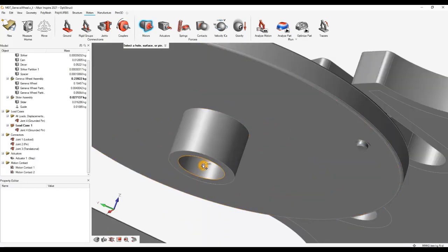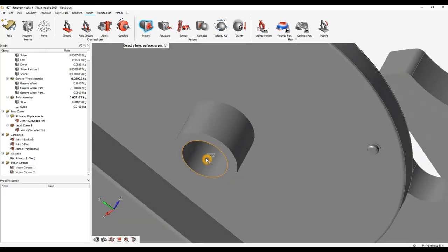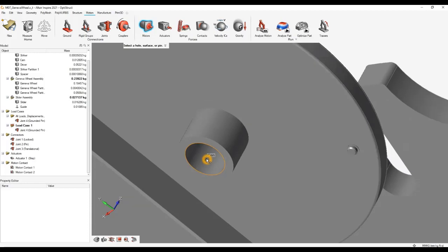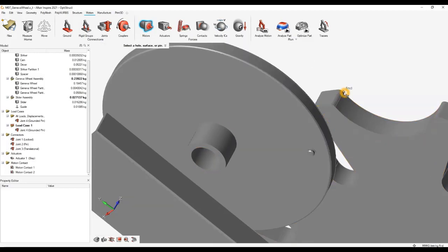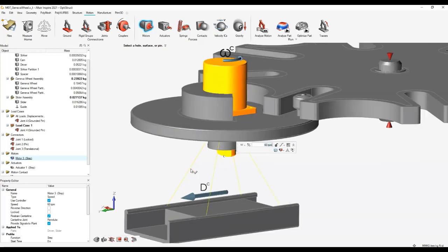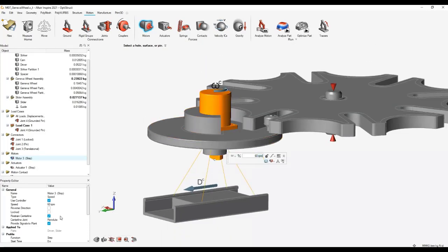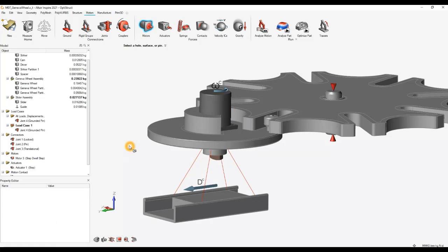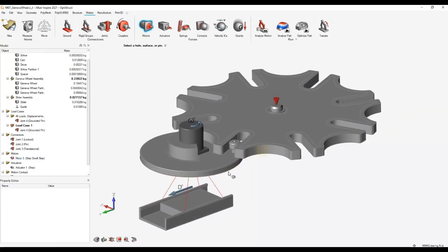Let me hover onto this center, and there is an intelligent feature recognition tool in Inspire in that it recognizes when you've reached the middle of a line, or let's say the end of a line, the center of a surface, or the middle of the surface as well. So from here, I just want the center of this surface, and I'll connect up to this surface too. And with this center, what we wanted to do is same again, make sure it's a step dwell step function. So we'll have it 0.5, let's make this one 2, and the step off duration will be half a second again. And once we're done with this, let's solve for it.